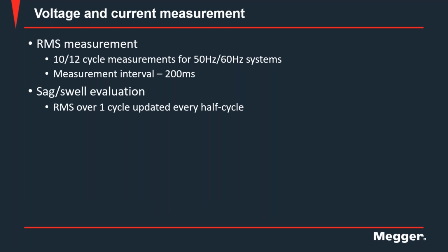The IEC 61000-4-30 gives the requirements, and one of the requirements is for the RMS measurement interval, which is 200 milliseconds. So that's supposed to be the measurement interval for RMS value measurement. All of these values that are calculated over every cycle need to be aggregated to give you a 12 cycle measurement value. And that's the requirement as per the standards.